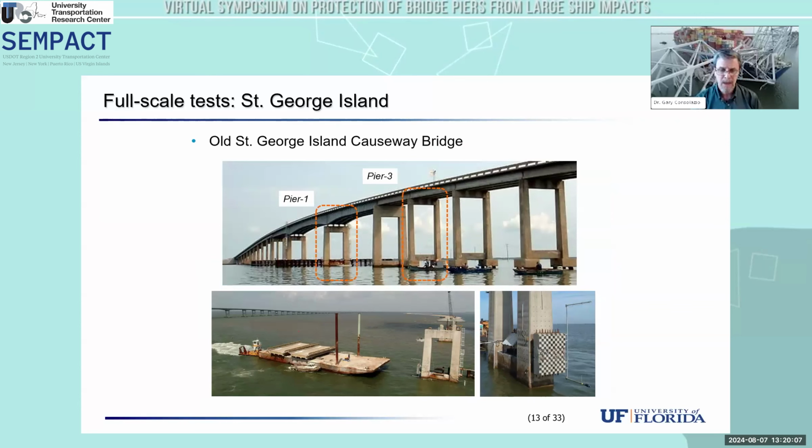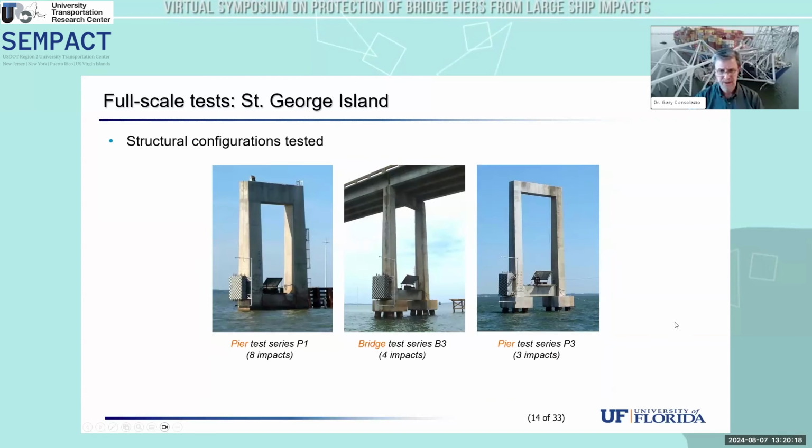We used a 600-ton barge, and we had a variety of different types of instrumentation on the structure, including load blocks, accelerometers, displacement transducers, and a lot of other types of sensors. We tested the bridge in 3 different configurations, 2 different positions, but 3 configurations. So we tested the channel pier in isolation.